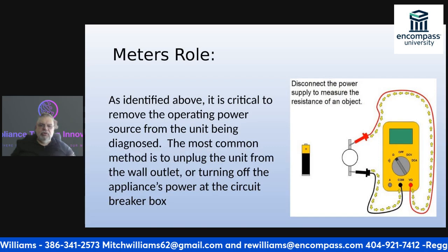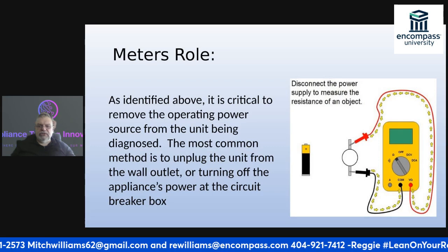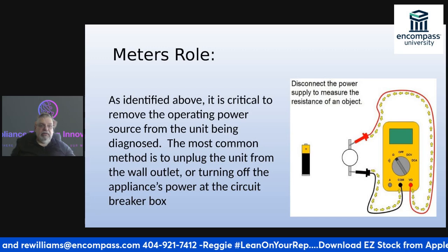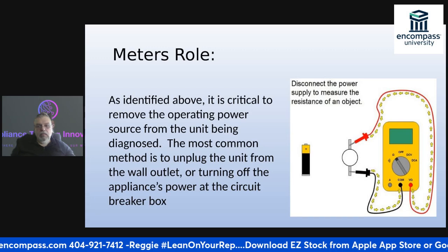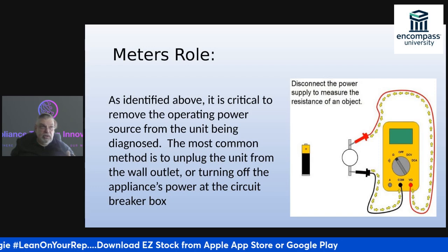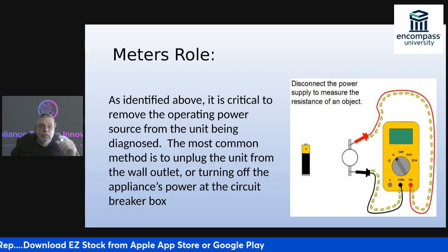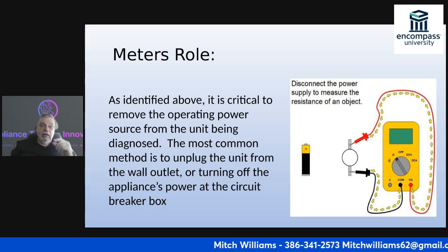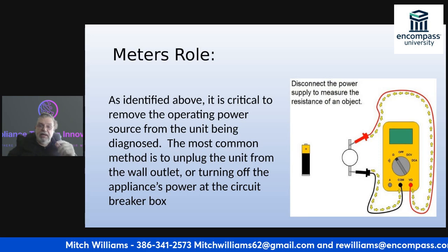If I'm trying to measure resistance, I will blow my meter up if I have it plugged in. The one that I like to use has a little fuse in case I get stupid one time and forget to do it. And I have blown that little fuse a couple of times because I got in a hurry. We want to make sure that everybody's safe.